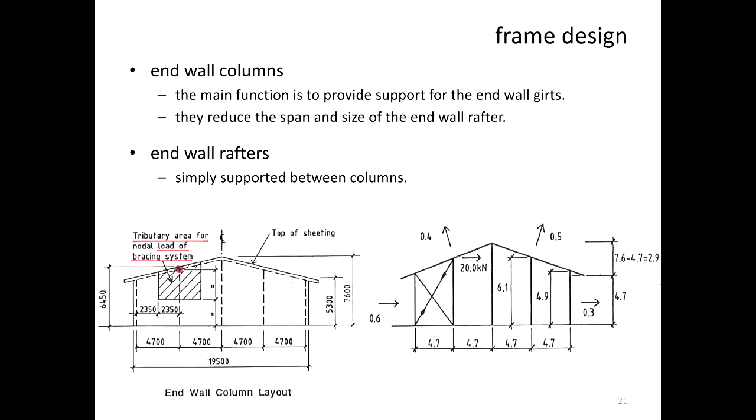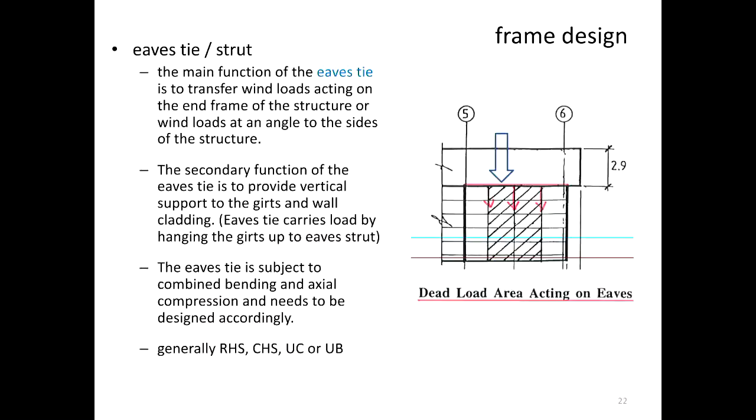That talks about nodal load, which is not quite relevant to you, so I'll leave that out. Every section you can brace, not just which. It depends on the design. Sometimes if you have maybe 1, 2, 3, 4, 5, they'll brace bay 1, bay 3, bay 5, and 2 and 4 is not braced.